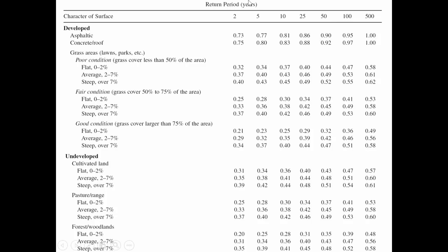Did you have a comment that you were going to add? Okay, all right. Another part of it is just that the 50-year storm is more intense. So when you've got a greater intensity, maybe it's not just the quantity of water, but the water is rushing over the surface more quickly, so it's spending less time. There's less time for it to saturate downward. Okay, so that's the trend we saw as we looked through the columns.